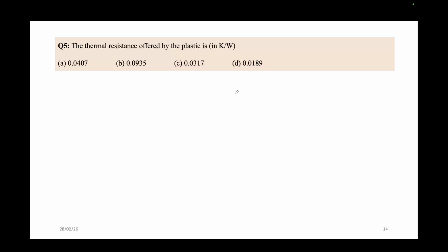So I am writing this formula again. R conduction is ln(R2/R1) divided by 2 pi k L. R1 and R2 you know.